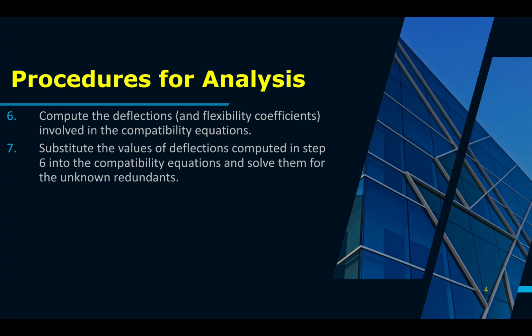Okay? And then so number 7, substitute the values of deflection computed in step 6 into the compatibility equations and solve them for the unknown redundants. So basic na lang siguro yan. And then after these redundants have been determined, the response characteristics or the reactions, shear and bending moment diagrams or member forces of the indeterminate structures can also be evaluated either through equilibrium considerations or by superposition of the responses of the primary structure due to the external loading and due to each of these redundants.